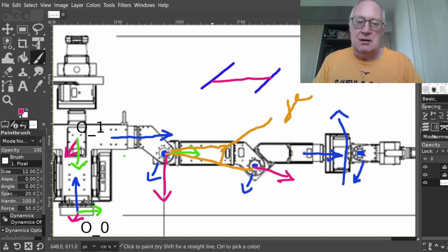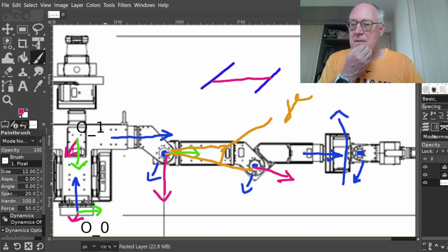Yep. D is 0, alpha is 0, and A is a distance of 313 millimeters. So then we can add that into our figure. Theta 3, D3, A3, alpha 3, T dot A3. And we plot the coordinate system. And I make that one a little bit thicker. So we'll see what it looks like.